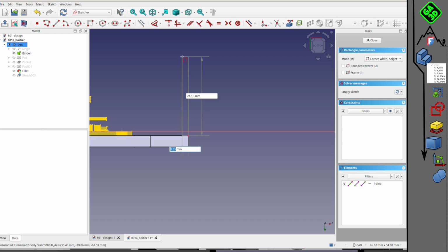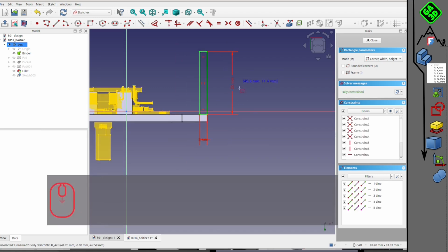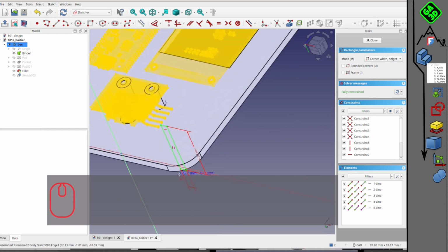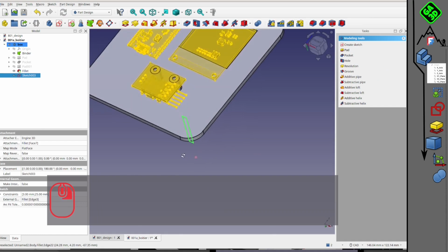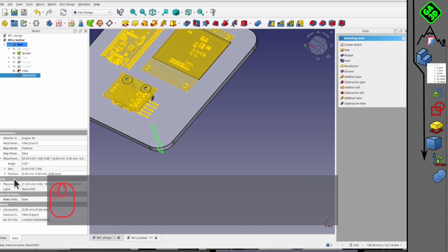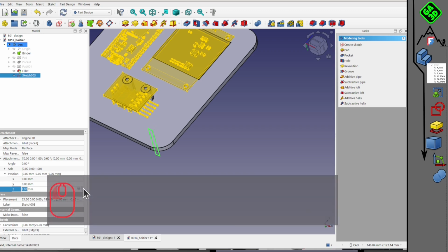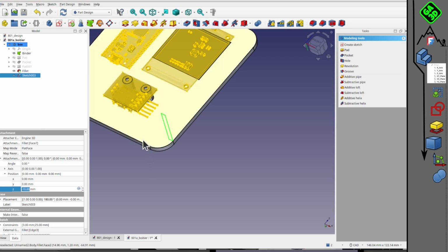So we're going to reposition our sketch so it starts here. How do you do that? You go directly here in attachment position, and then you can actually move your sketch relative to the reference element you used. So the reference is this face here, face 7. We can see it here directly in the software. And then we move 10 mm, so we start here.